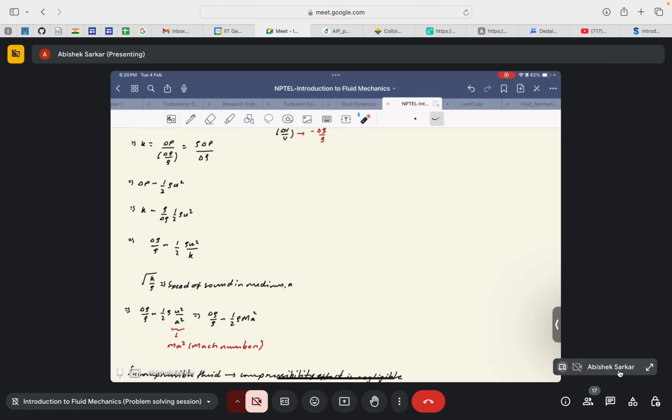Pressure is an interesting parameter because it itself does not have any characteristic scale, but it depends on the parameter that governs the flow. If the flow is governed by the kinetic energy of the flow, then the pressure would vary as the kinetic energy of the flow. For most of our studies, at least in this course, our pressure would depend on the kinetic energy of the flow.